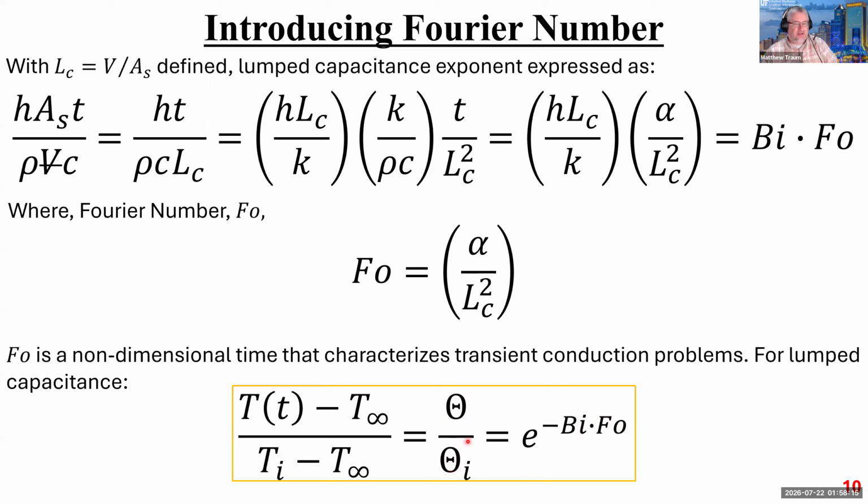right? So we're not going to carry it out, because we don't talk about Buckingham Pi in this class, but if you were to put together the set of important experimental variables, and then do the Buckingham Pi analysis, what would pop out is this exact expression, right? So this temperature ratio, and then the Biot number and the Fourier number. Of course, you wouldn't know the functional relationship from the Buckingham Pi theorem, but you could run an experiment to figure it out. But I think it's just super cool, right?